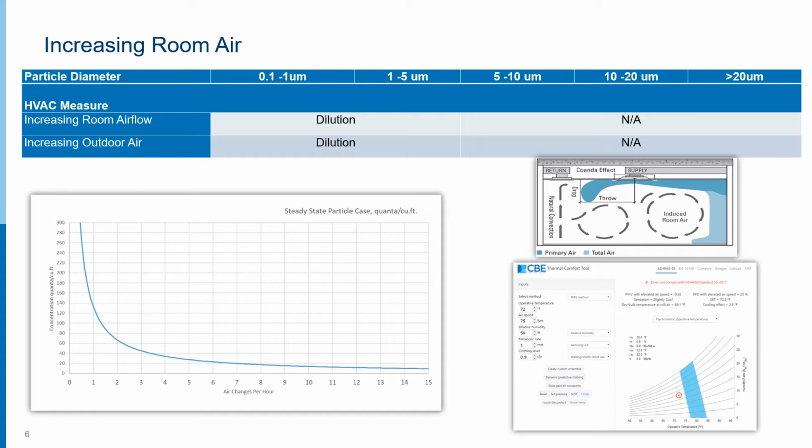The air in a normal, comfortable room does not have a lot of velocity. In fact, we're deliberately trying to avoid that. The goal is to mix air and achieve an average room velocity of 20 feet per minute or less. The reason being, velocity in the air is uncomfortable. If you had 50 or 75 feet per minute of average velocity in a room, then the occupants would be cold and they would complain. So we generally don't have that. And that's kind of an important point.